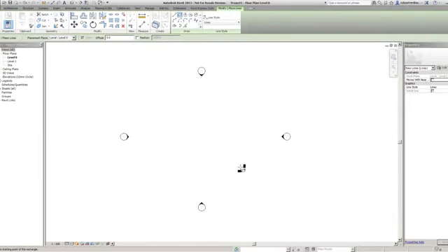I left click on the rectangular mode, and I simply start my rectangle and start moving it. Now, as you can see, as I move my mouse around, we have these 2 little dimensions that pop up inside the rectangle. These are what we call temporary dimensions. Temporary dimensions pop up all the time within Revit, and they're always there. They're always helping us and they're fantastic. And as you can see, as I move my mouse around, it gives you a good idea of both the horizontal length and the vertical length of this rectangle.